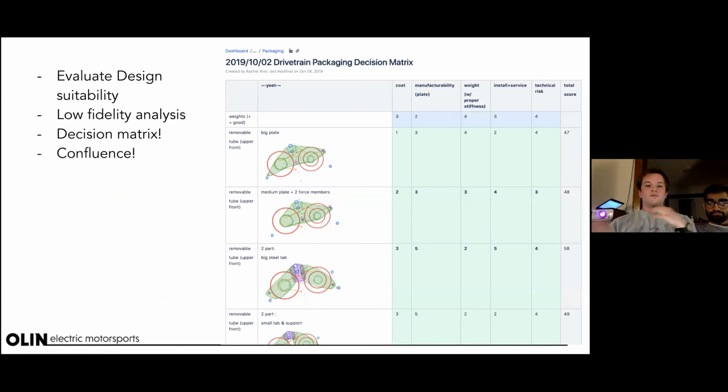And the way that you restrict that really whacky mentality and crazy thinking is you do something called the design matrix, or a decision matrix. Also not going to get into this super in depth, but you essentially put attributes that are relevant to your requirements, as well as general mechanical attributes such as cost, manufacturability, technical risk, things like that. You put those along the top and then weight each of your potential options based on how satisfactory it would be in each of those categories. Multiply the weights represented in this blue row down, and then sum them across.